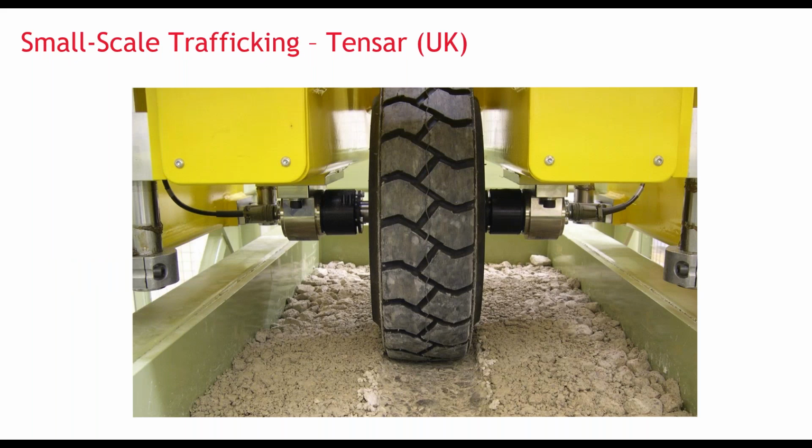Having focused in on stabilization using geogrid, the next question is how different geogrids, even integrally formed geogrids intended for stabilization, compare in performance. Is one geogrid the same as another? To answer this, we'll look again at geogrid under a wheel load. These pictures are from a test rig at Tensar's lab in the UK, where we can simulate field conditions to test products. We've placed a compacted gravel layer over a soft clay subgrade and then repeated the setup, adding 2 different geogrids. Then we load the wheel and run it back and forth over the test section to simulate traffic.